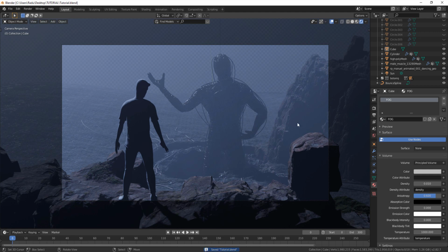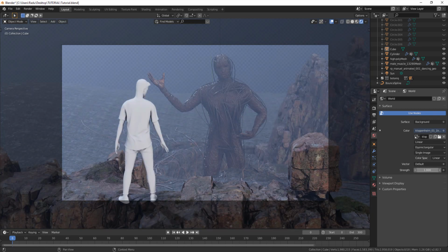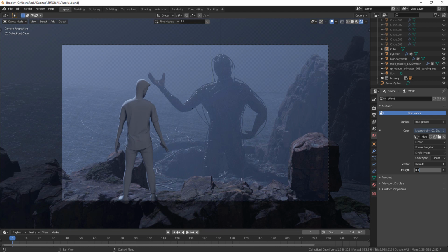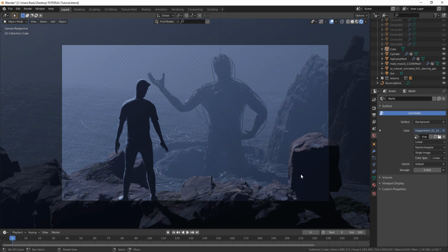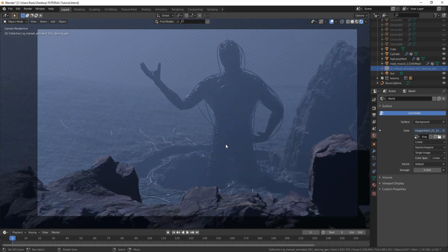At this point, I have a good direction for the sun, and what I want now is to add some of that HDRI back into the scene. But I don't want to put it to 1 because this is too much light. This is not a night scene anymore. So what I want to do is go incremental, like 0.1, 0.2, and what I'm looking at when I'm doing this is, forget this guy because he's white, and let's not get the point across.